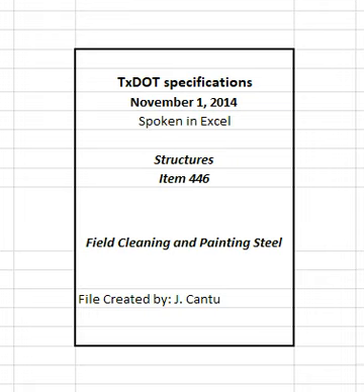4.7.4.5 Paint systems. 4.7.4.5.1 System 1A, Overcoating, 1 coat. Apply at least 4.0 mils dry film thickness, DFT, maintenance overcoat to all surfaces to be painted. 4.7.4.5.2 System 1B, Overcoating, high corrosion environment. Penetrating sealer. Apply 0.5 to 1.0 mil DFT of penetrating sealer to all surfaces to be painted. Prime coat. Apply 4.0 to 8.0 mils DFT of primer to areas that have received tool cleaning and to other areas where there is no existing primer. Appearance coat. Apply 2.0 to 6.0 mils DFT of appearance coat.